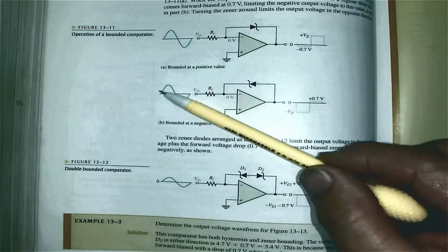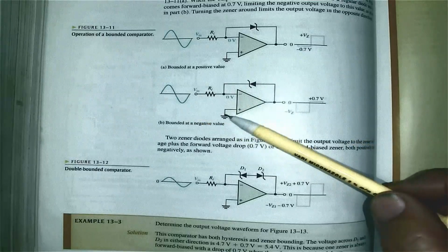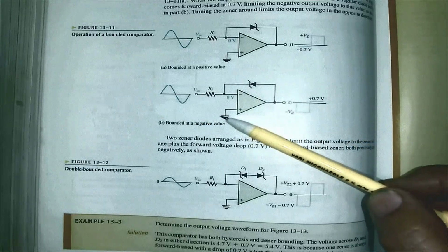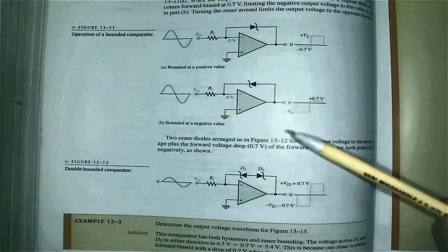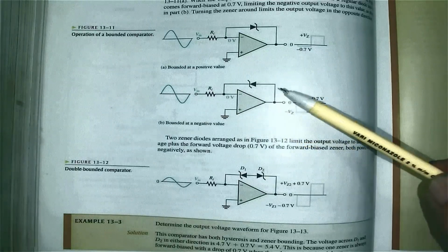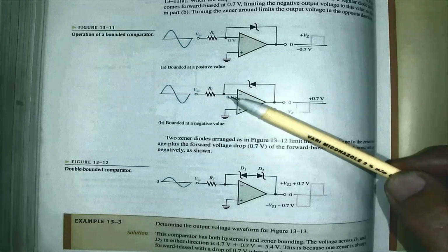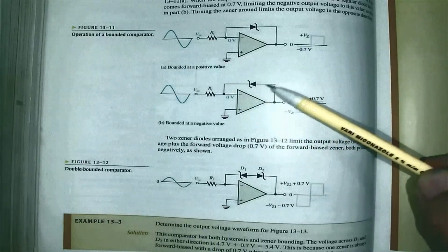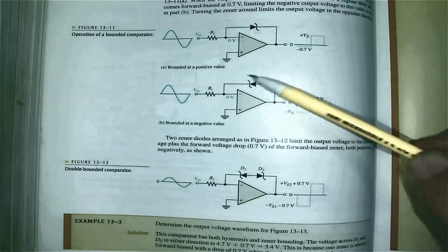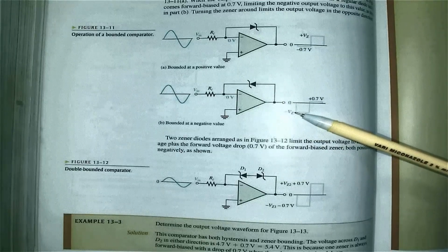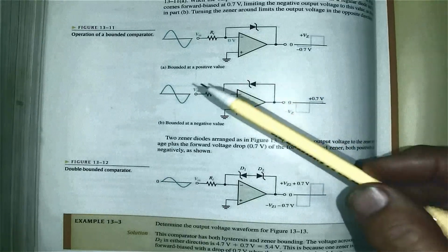Again, if my input signal goes positive with respect to this reference value, what will happen? The output will go negative. All right, there's 0 volts, it goes negative. What can I say about the Zener diode? There's 0. How does current flow? Flow from positive to negative. The Zener diode is reverse biased. It will go to minus VZ, all right?